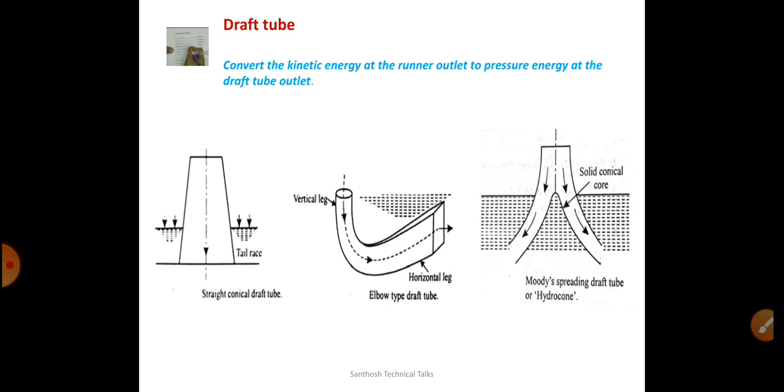In reaction turbines, we are using both pressure as well as kinetic heads, whereas in the Pelton turbine, they are using pure kinetic energy with a low rate of flow. The impulse turbine does not have a draft tube for converting the kinetic energy into pressure energy, since it is open. Pelton turbines are generally open in the tail race.